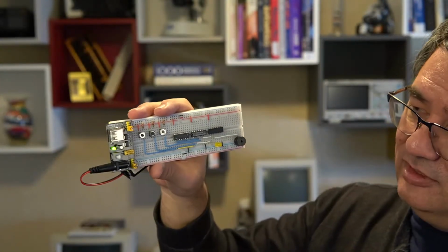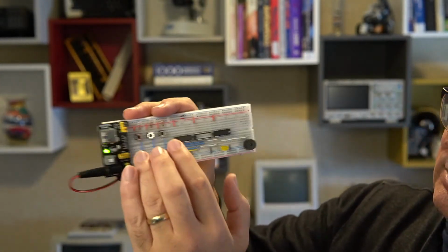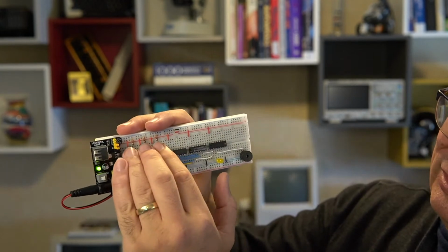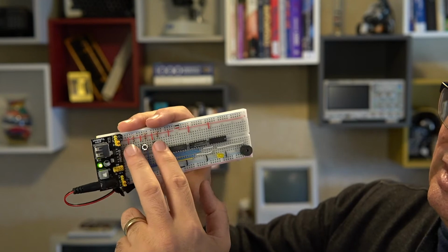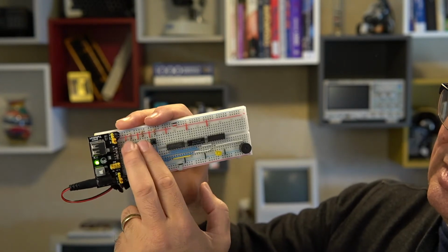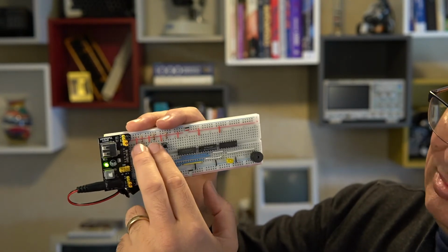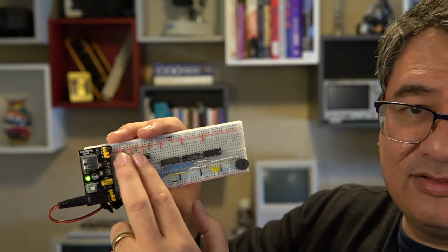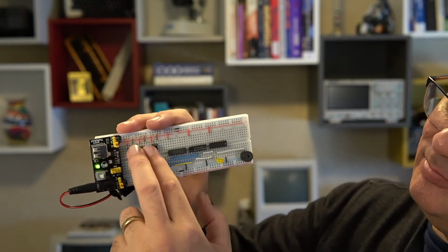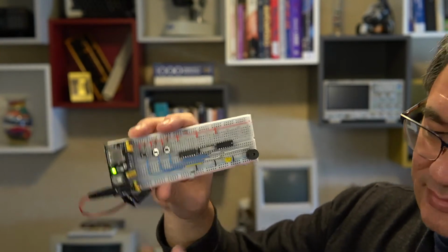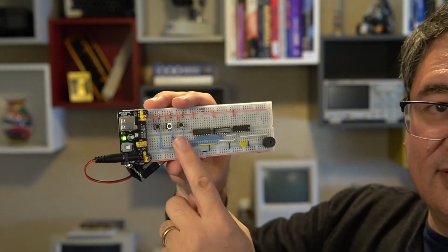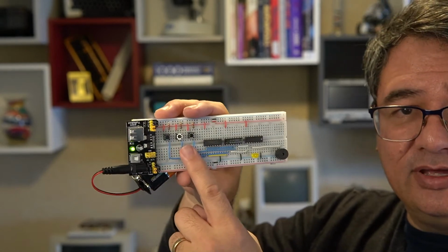Now I should have had this camera up so you could see it. But you could probably hear it, right? So all 3 of them pressed, light and sound. A and C, light and sound. A and B, nothing. There's a little bit of a chirp because I can't press these buttons exactly simultaneously. But when I do have both of them pressed, nothing's happening. So this implements that logic circuit that we analyzed the truth table for.